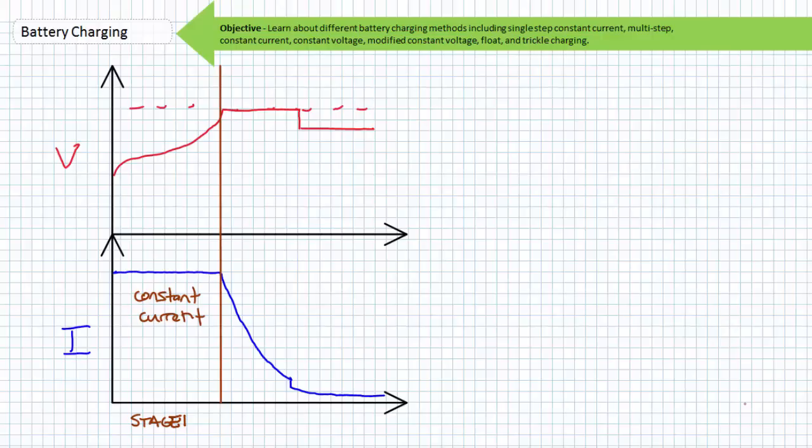This maximum safe current value ensures that the battery is receiving a reasonable quantity of electrical energy, yet is not placed at risk of damage due to overheating or destructive effects. As can be expected, battery voltage will rise during the initial constant current charge stage. This first stage takes up roughly half of the required charge time and is sometimes known as the bulk stage, since it applies the bulk of the charge.